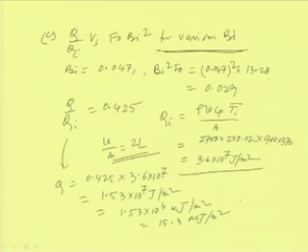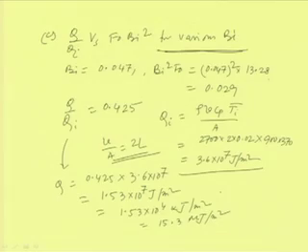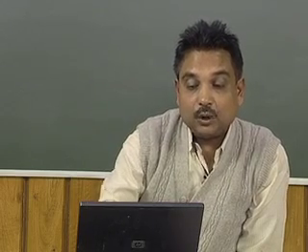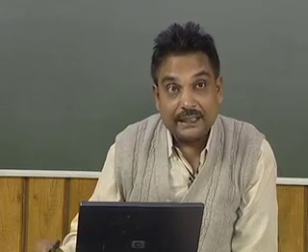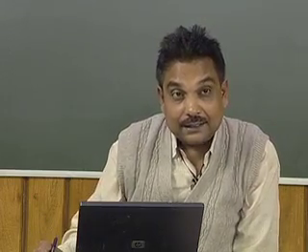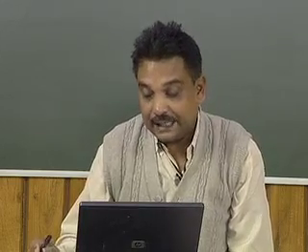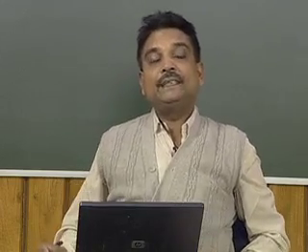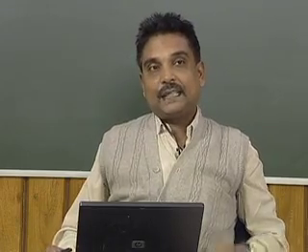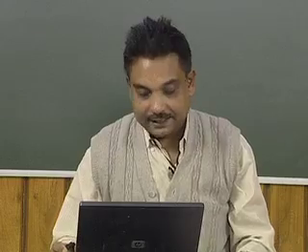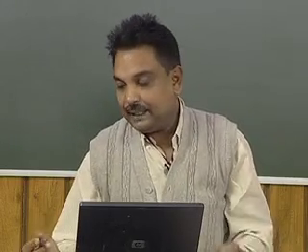Now, what is happening? We can calculate that this much amount of energy is being lost from the solid boundary. We can see that the lost energy is about 42.5%, because Q by Qi is equal to 0.425. This is 42.5% of the initial internal energy for this case. Now, what we will do is repeat this problem for the cases of a cylinder and a sphere.